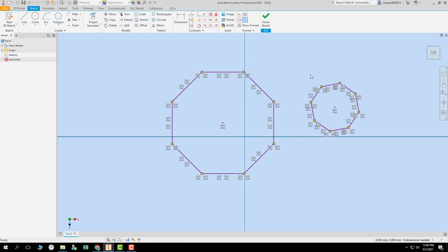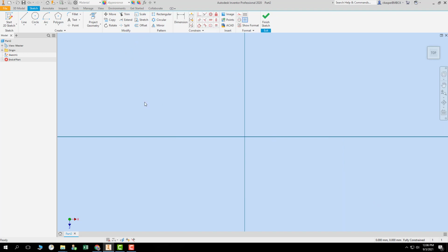So I wanted this to be straight. Well, that's where these come in. My top is upright. I go over to, say, I could choose vertical or horizontal. Doesn't matter which one. I'm going to choose horizontal for this one, and I'm going to click on a horizontal line. And now it's horizontal. This one here, if it's a little bit crooked, I'll click vertical and hit vertical. It already is constrained vertical, so I don't have to. Okay, so I'm going to escape like crazy, highlight this and delete it.